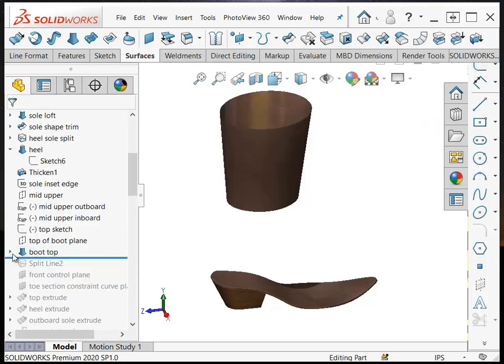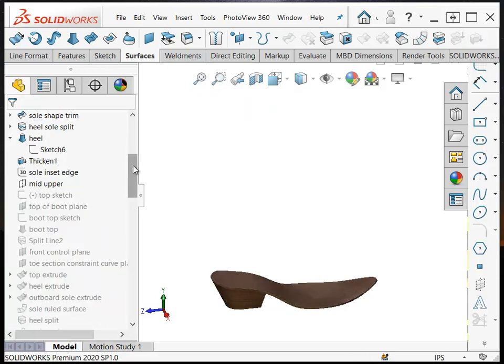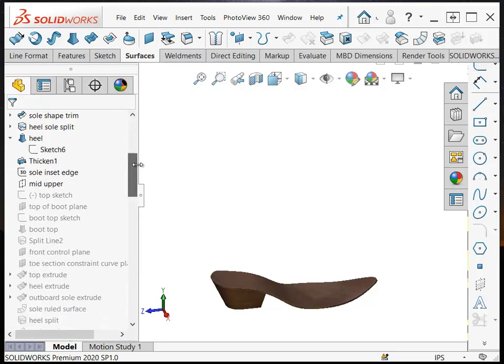There's something that's a little bit odd going on with this. It lists these as three separate sketches, even though they're really just two different profiles. Usually, SolidWorks allows you to roll back between the feature and the sketches to temporarily unabsorb those sketches. But when we do this in SolidWorks, we get a really odd result. The rollback bar just goes away, and the sketches that we're looking for aren't here.